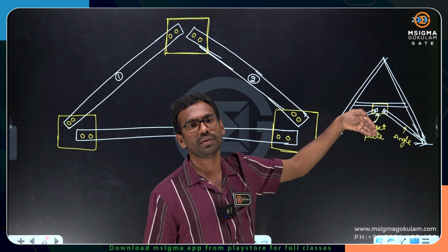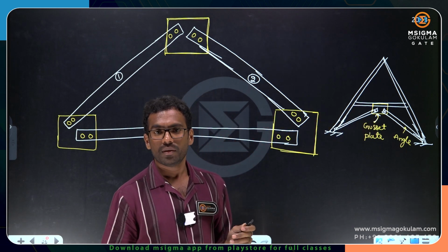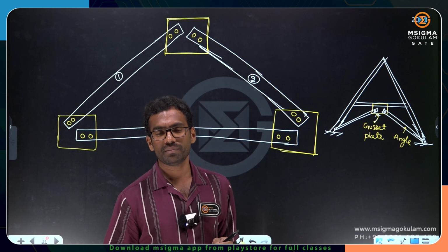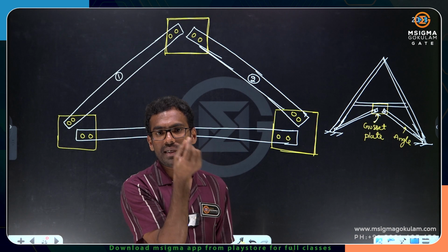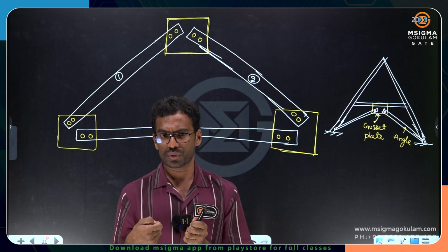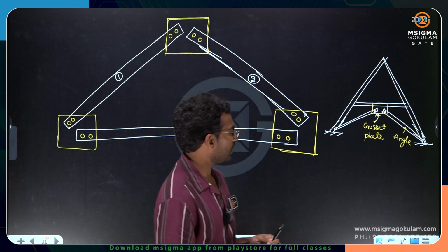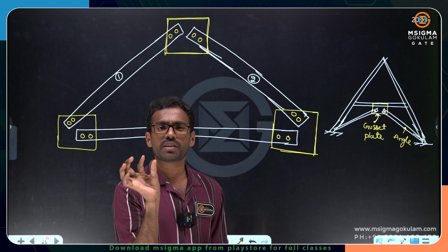It's a very simple thing you have to understand. So whenever I want to improve the efficiency of an axial force member, provide a larger area in the connection. Provide a larger connecting member in the connection so that it can transfer more force. Is it clear? Right. Okay.